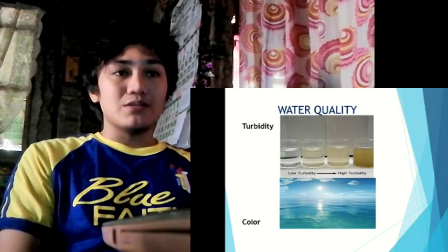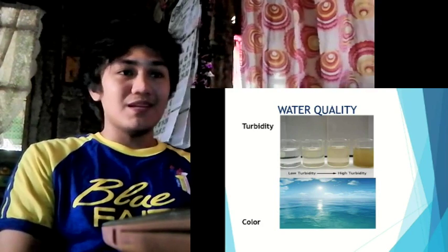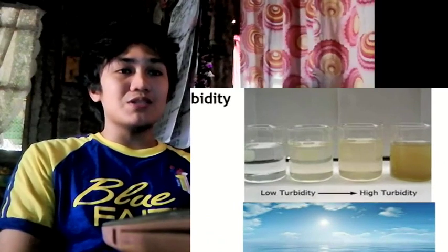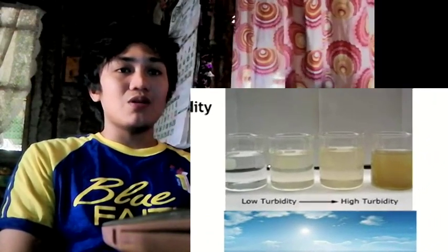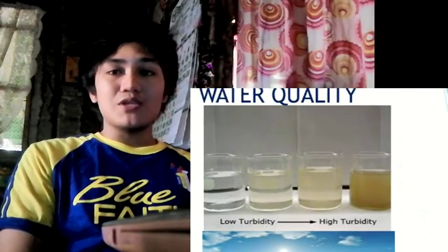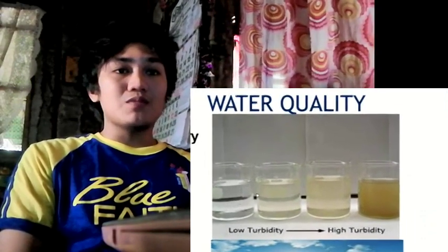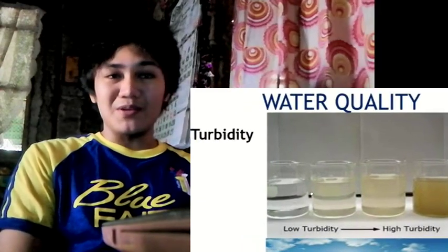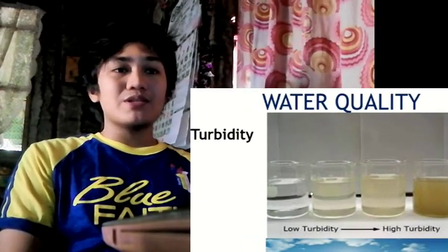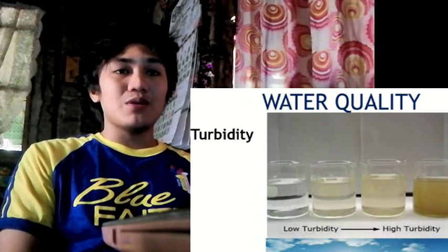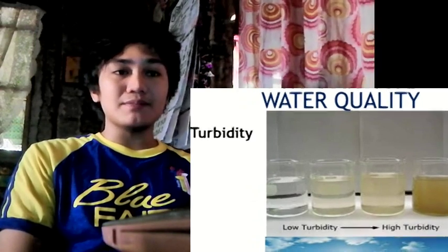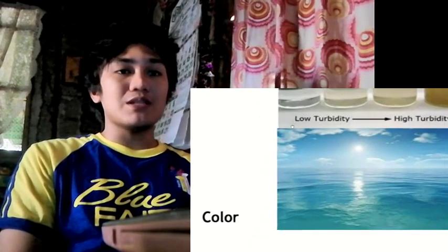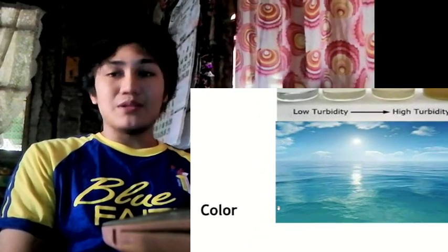Organic materials. Turbidity. Color. Dissolved organic material from decaying vegetation and certain inorganic matter cause color in water. Occasionally, excessive blooms of algae or growth of aquatic microorganisms may also impart color. Color itself is not usually objectionable from the standpoint of health. Its presence is aesthetically objectionable and suggests that the water needs appropriate treatment.